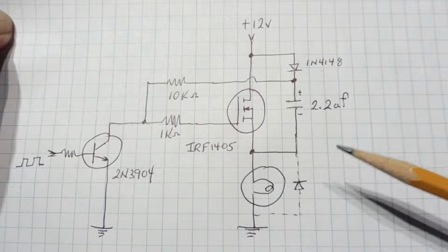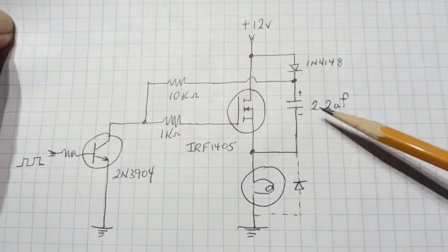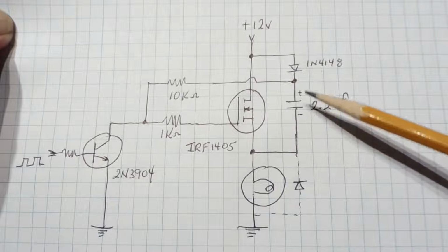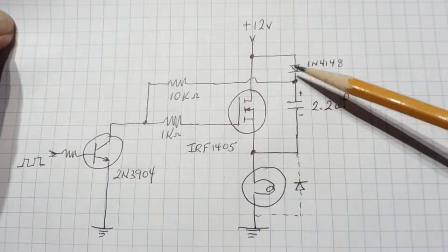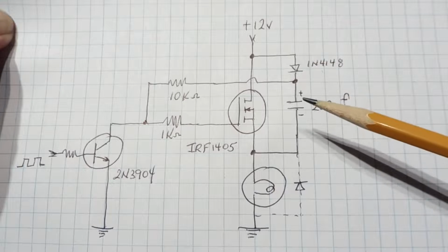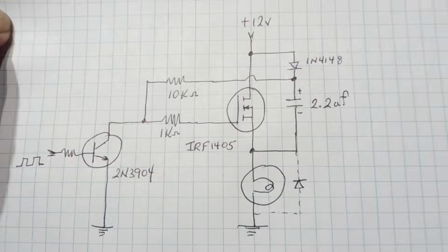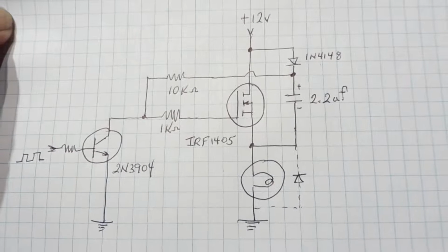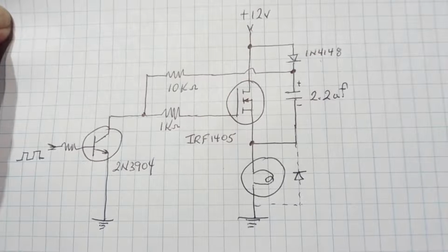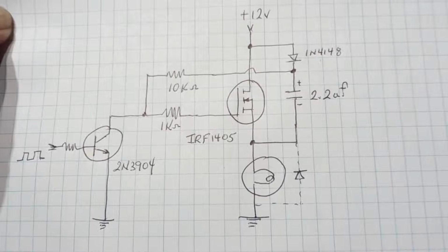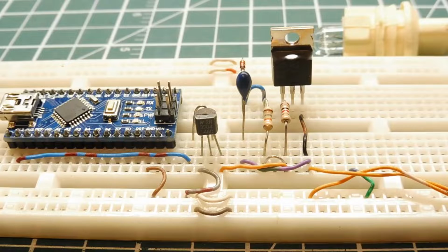So you can see if you keep the load on, eventually this capacitor is going to leak out through the reverse leakage of this diode, and it's going to leak down. So this is an on-off circuit. That's my circuit there for my bootstrap circuitry. I hope this gives you some information on how you can build your own bootstrap circuitry to build an N-channel high-side switcher. Okay, now you know how a bootstrap circuitry works.